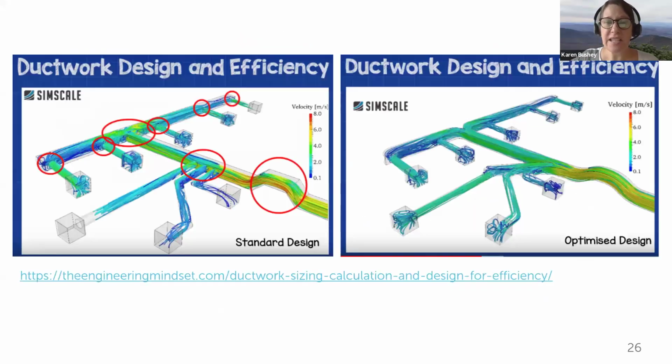The other thing on the flex duct, I think we go to that next, do we, Karen? Almost. I put this slide in there because I thought it was a great slide to demonstrate what Mark was just talking about with the efficiency of the fittings. This was an analysis done by some students using some airflow analysis software. And you can see with all of these sharp fittings and the bull nose T and the straight 90 takeoffs all in a row, some of these registers, the air isn't even getting there. And you compare that to a system that really was designed for efficient distribution with all of the Ys and sweeping elbows, and you can see how it really does a much better job of getting the air to where it is meant to go.